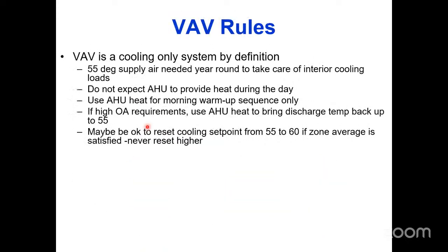All right. That's the ways we can control capacity. So modulating chilled water is good. Lots of stages of fixed speed compressors is good. Fewer stages of fixed speed compressors, but then adding a digital scroll or inverter on the lead compressor. Those would be your three ways in a modern system to get that done.